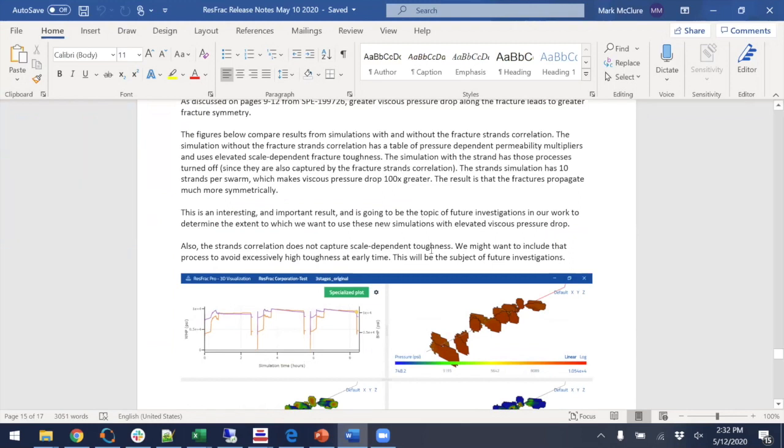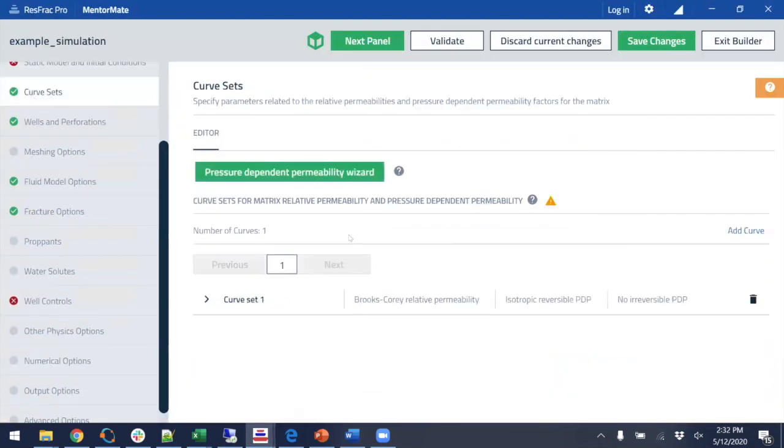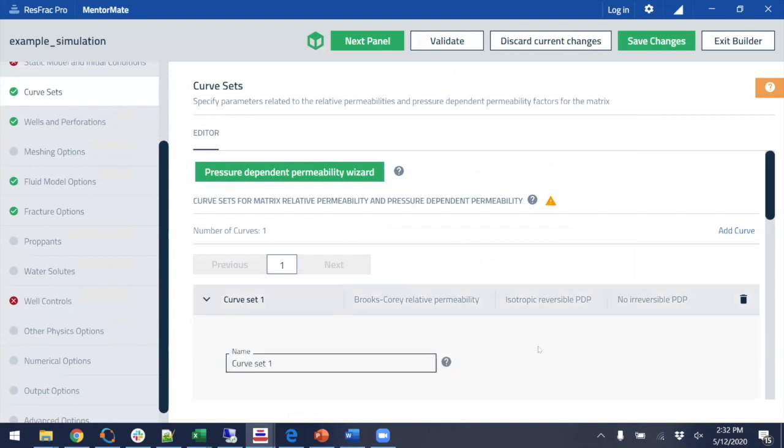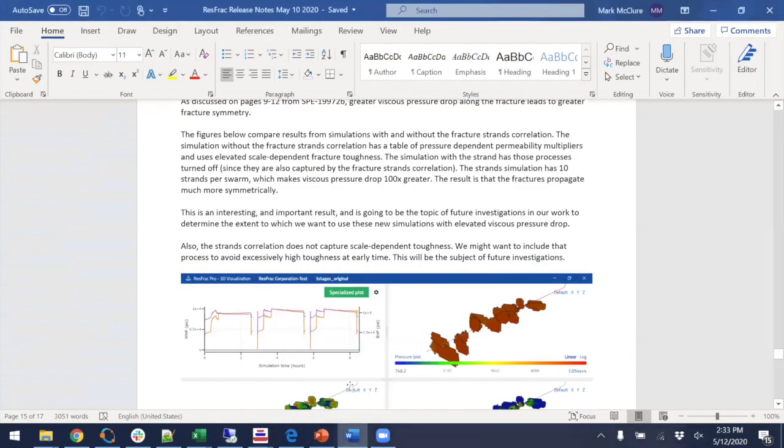We mimic that as a pressure dependent permeability. Again, we already do that: we already have tables of pressure dependent permeability during fracturing to account for accelerated leak off. When the unpropped fractures close, we assume they don't contribute to production, but we think they're important for leak off.